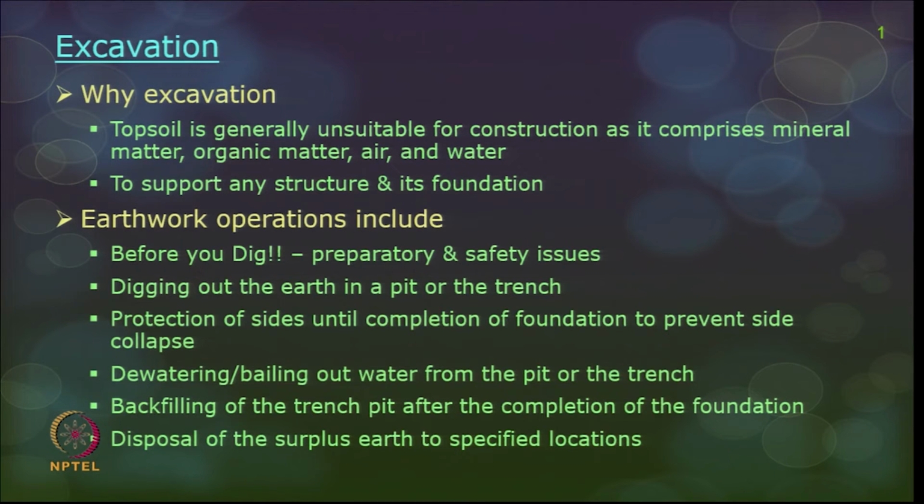Now, why should you go for excavation? The top soil as such is not suitable for construction and it comprises mineral matter, organic matter, water, air, etc. That is why it is not really suitable for construction, and hence the soil has to be removed.